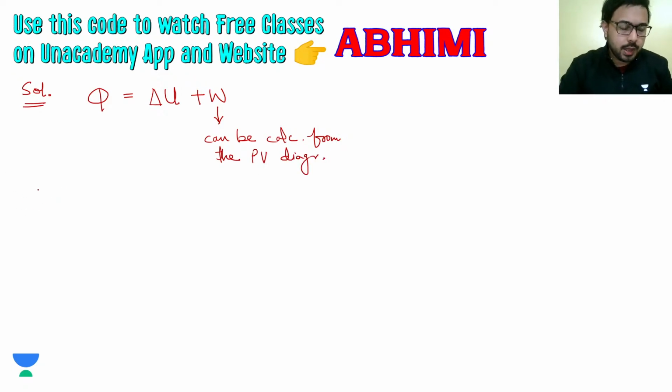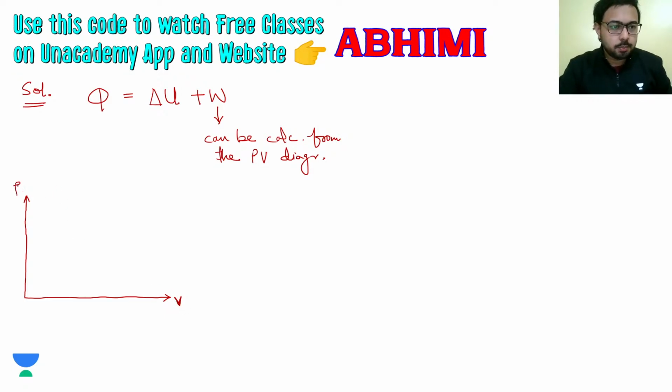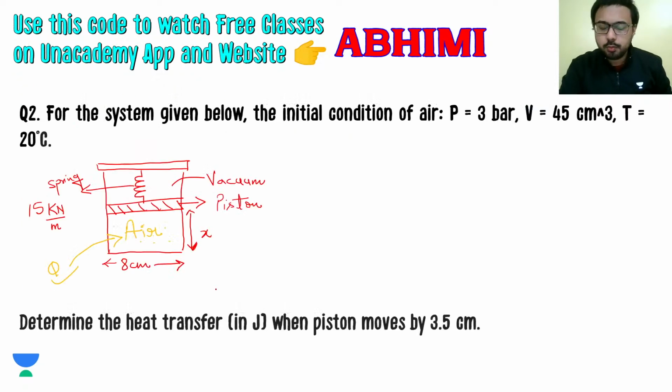So let's draw a PV diagram so that we can calculate work done. This PV diagram will be very helpful whenever you encounter these spring piston cylinder questions in thermodynamics. You have to draw the PV diagram to quickly do questions and get the work done, because the area under the PV diagram's process gives you the work done. Let's take pressure in bar because the values are given in bar, and volume in meter cube, but it is given in centimeter cube, which we can change.